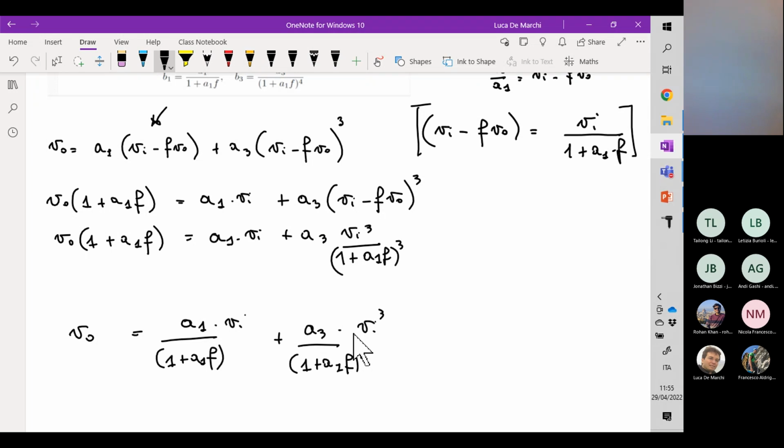Or if you want, since typically the phase shift is negative, this phase margin here is basically the difference between the phase curve related to T of j omega, so the phase of this quantity, and the minus 180 degree line, computed specifically at the angular frequency omega null, which is the one which corresponds to the unity of the loop gain.